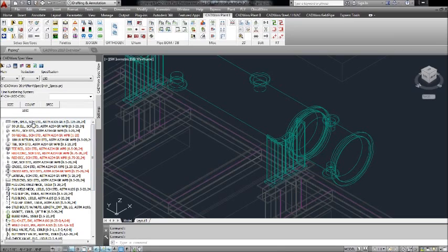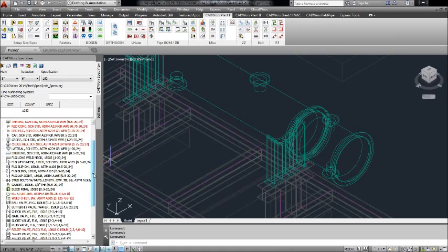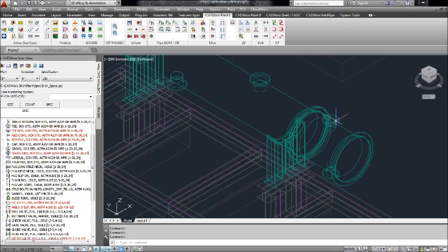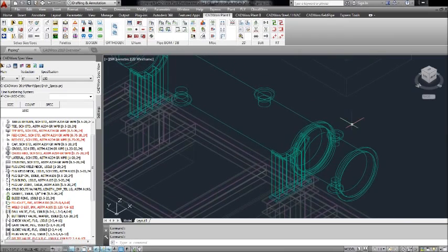What I'm going to do, though, in the old system, I would have to start by putting on a gasket here. I'm going to come off the top side of this tube and shell exchanger over here. And in the old system, I would need to do a lot of block modeling. I would come over here and get my gasket and put it on that nozzle, get my flange, put it on that nozzle, and then start routing with either my 3D router line or block modeling, doing a component at a time.